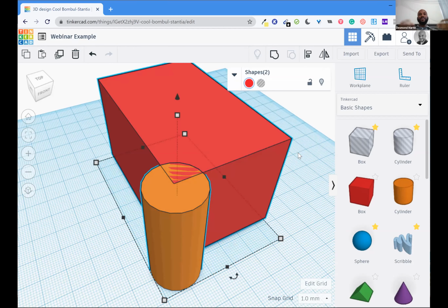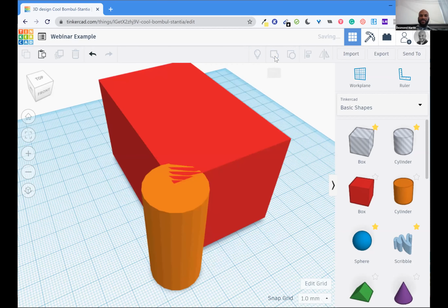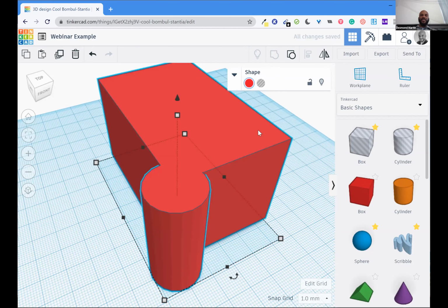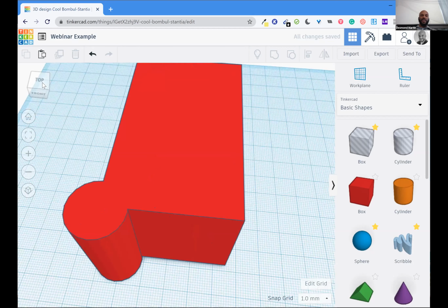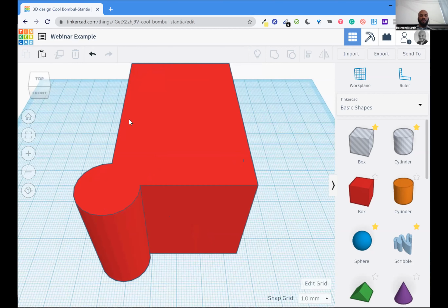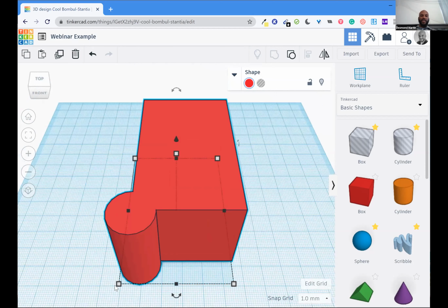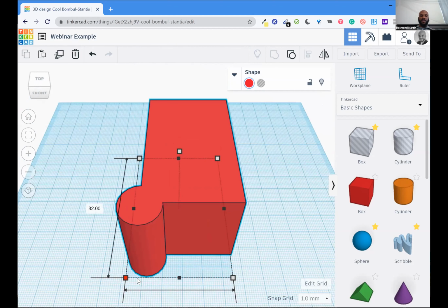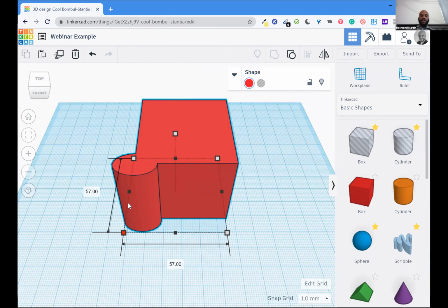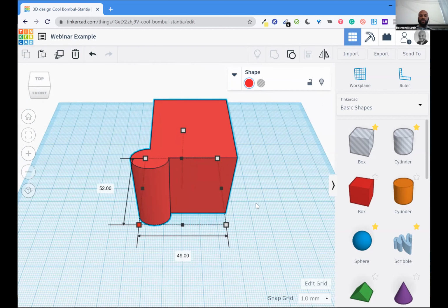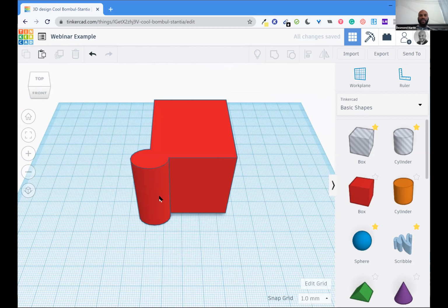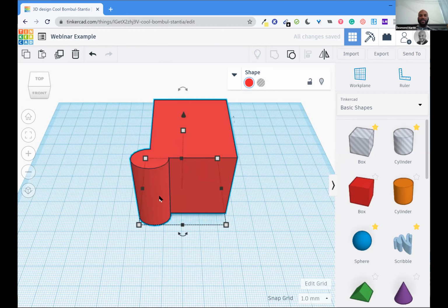By highlighting multiple shapes and clicking this tool in the bar, group, I've taken the two shapes and I've turned them into one shape, a more complex shape than we had before. And I can manipulate that more complex shape very simply. Everything is going to scale and follow what I wanted to do. So I've taken two shapes there and I've manipulated them, added them together.